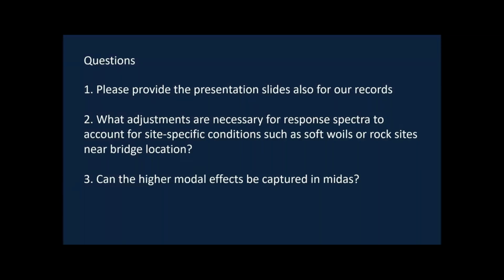This entirely depends upon the geotechnical engineer to let us know the average characteristic, or the average Vs, the shear wave velocity that we are getting in that particular structure. Depending upon the average shear wave velocity, the soil characterization is done to evaluate the response spectrum demand.